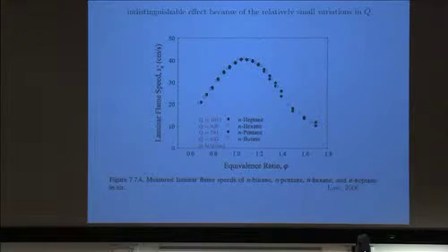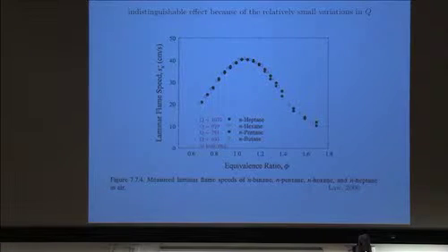If you now look at a different set of fuels where the heat release does not change dramatically from each other, you see that the flame speed also does not change dramatically from each other. And so the dependence on heat release, or the dependence on the adiabatic temperature through the exponential, is probably one of the strongest influences on the flame speed.